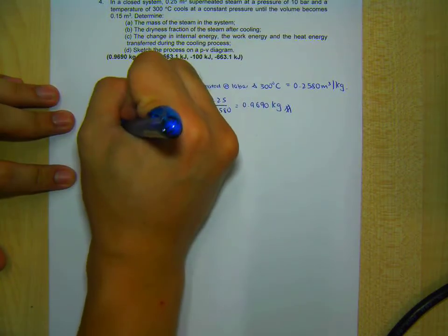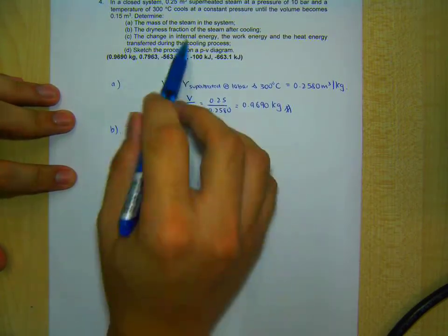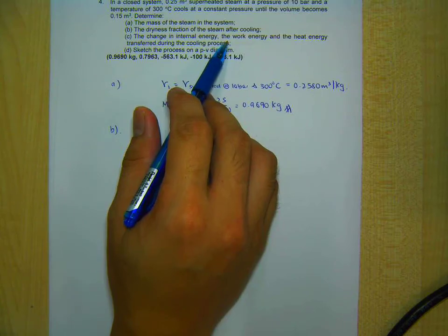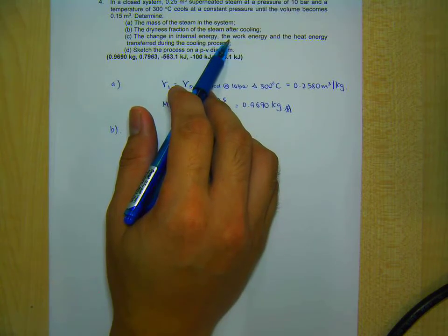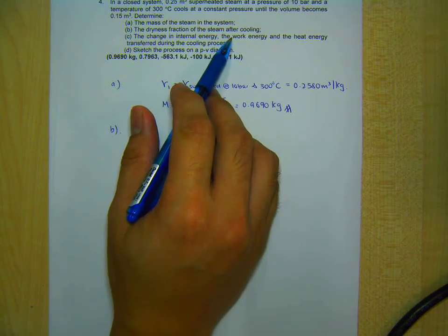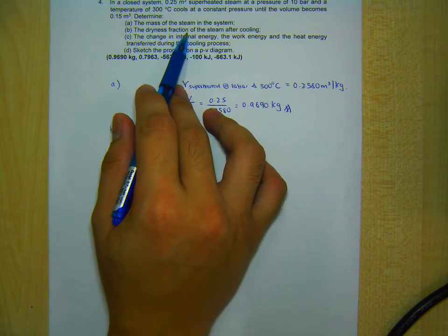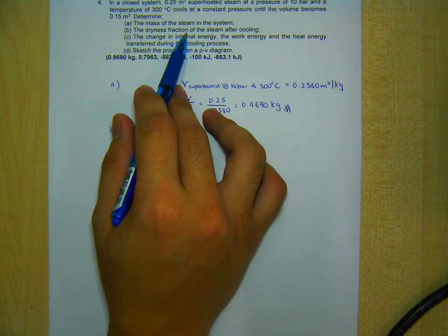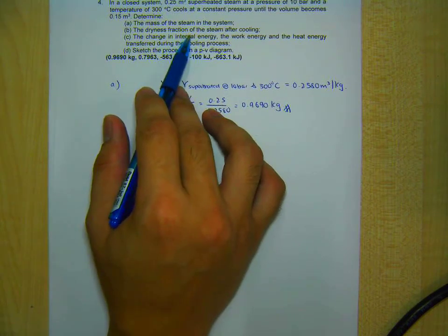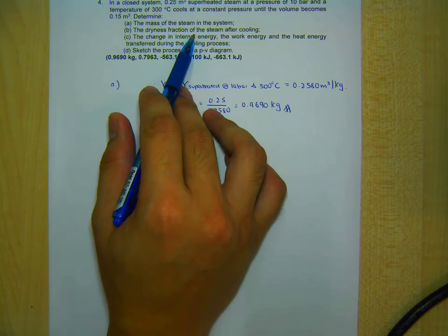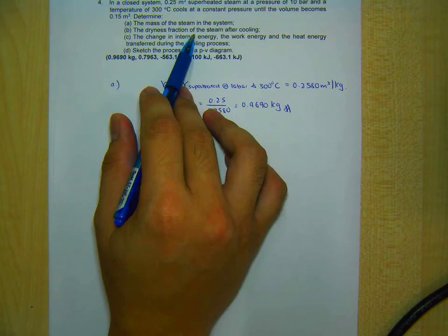Part B, the dryness fraction of the steam after cooling. Okay, in this case, after cooling, the steam actually becomes wet steam. So we will need both the specific volume of this second stage and also the reference vg. Okay, in this case the